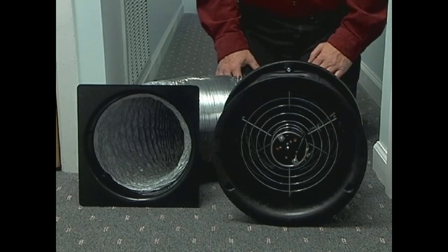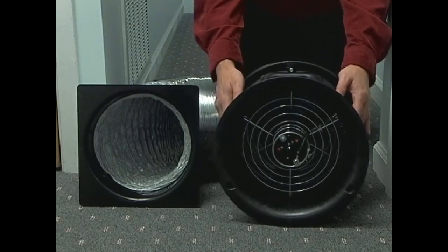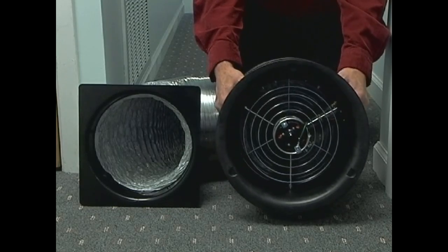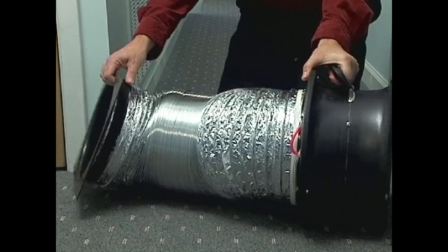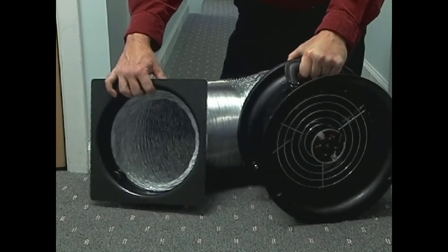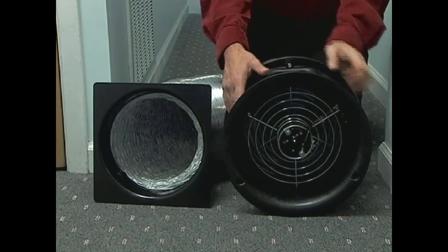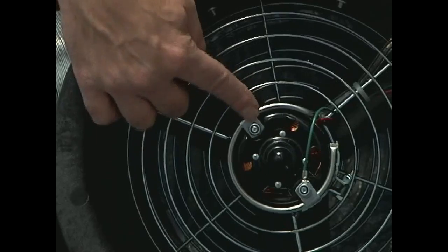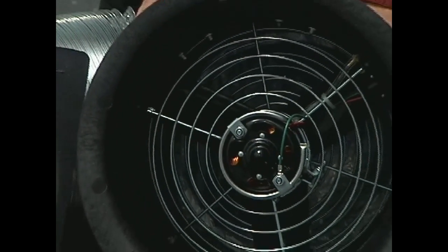Before we begin to set up for the test, let's familiarize ourselves with the various components of the duct blaster system. First, we have the duct blaster fan. The fan provides the airflow needed to pressurize the duct system. Connected to the back end of the fan is 12 feet of 10-inch diameter flexible extension duct. This flex duct is used to direct the airflow from the fan into the duct system. On the front side of the fan, or the fan inlet, you will see a stainless steel flow sensor mounted on the end of the motor. This flow sensor is used to measure the airflow going through the duct blaster fan.